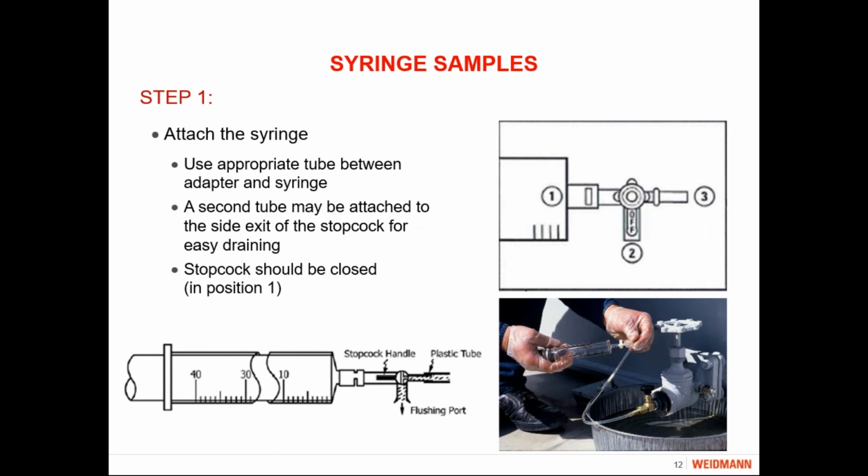There are 2 types of samples that you're typically going to take when you're sending these in for testing and analysis. The first sample we'll talk about is a syringe sample. The samples in syringes are basically used for DGA analysis, and there are some other specialty tests like a methanol test. Methanol is a byproduct of insulation breakdown, so it's a test you can do to assess your solid insulation condition. Those 2 require syringe samples.